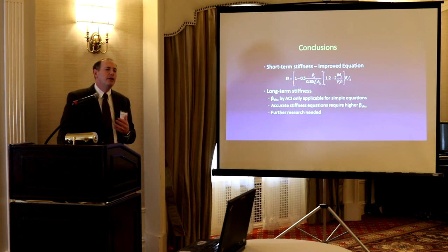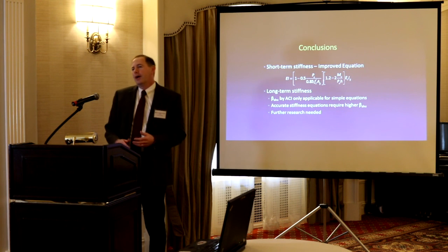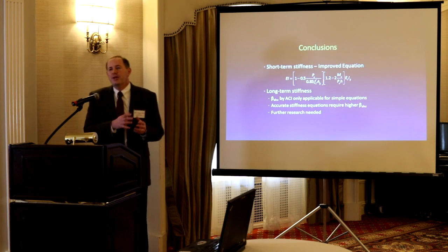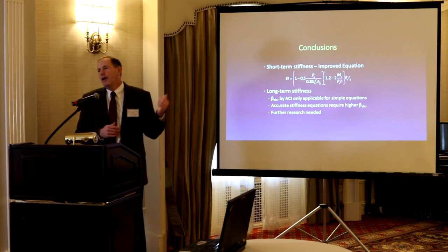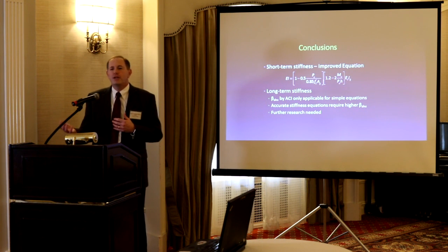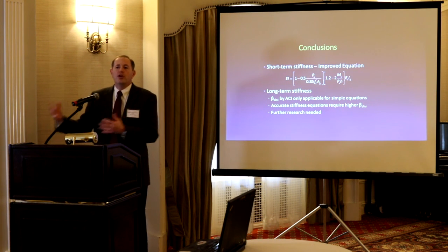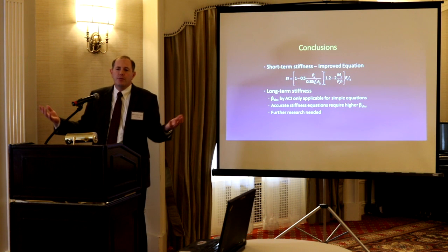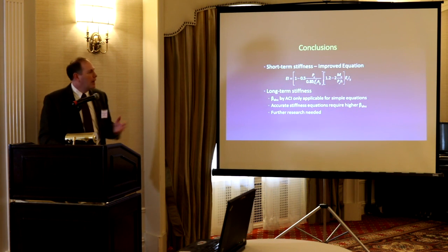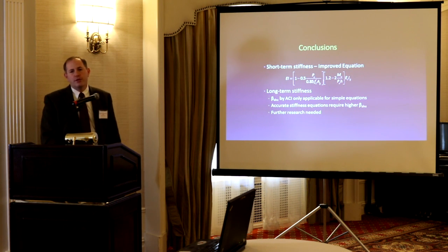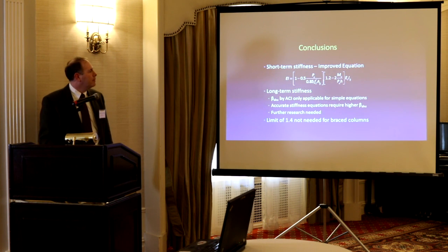Because again, we're talking about crack control, but if I'm a little off on the cracks, I don't want to have a column out here that we're significantly underestimating the moments, that we're going to put in the code that can be used for every building that we're going to design with. So I feel very comfortable in the short-term stiffness. We could codify that tomorrow. It's just the sustained effect we have to bring in.